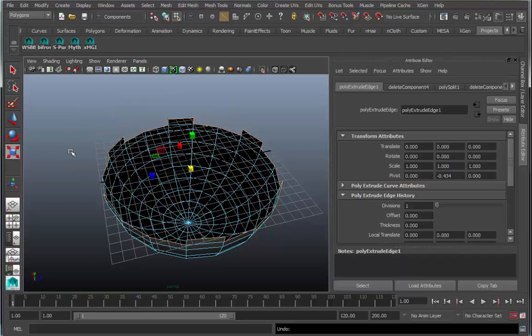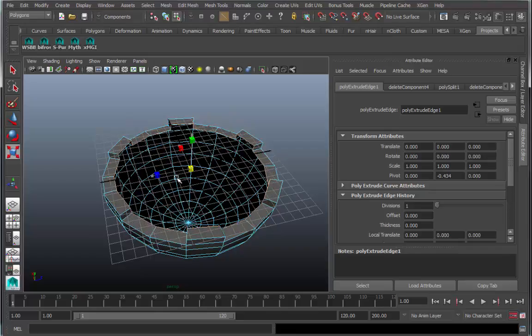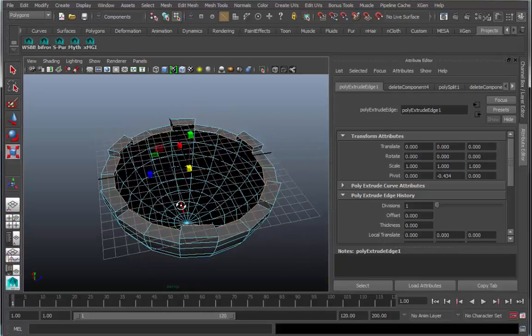Basically, you are still selecting all of these new polygons that you've made by the extrusion process, but we have one single controller right in the middle of the average of each of these edges' distance from the center, which happens to now be the center. So if I grab this yellow manipulator and drag down, I'm dragging everything in ever so slightly by scaling it all uniformly. And that's what we're looking for, so make sure you use that process.